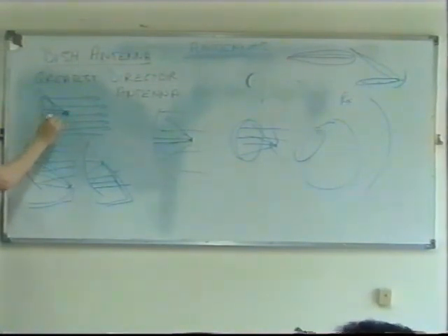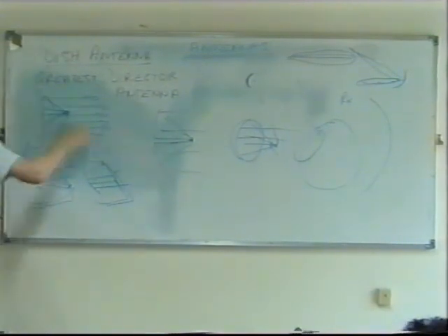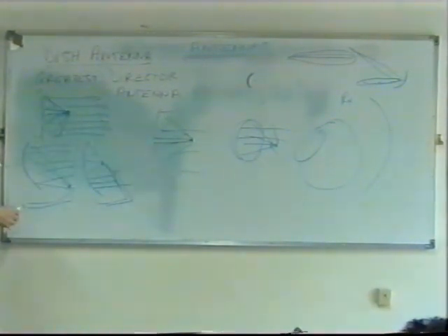Even the point itself is going to interfere. Anything in front of that beam is going to cause small amounts of energy, if it's a transmitter, to be radiated in other directions, and that will produce a side lobe.